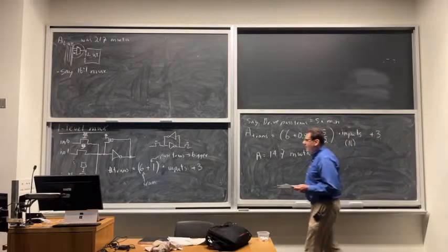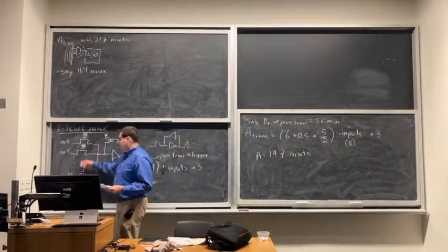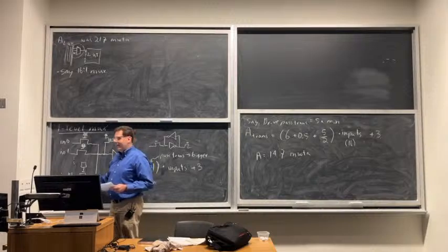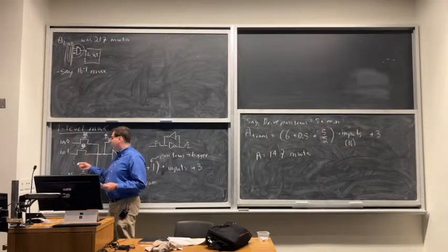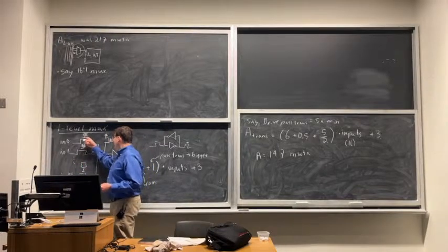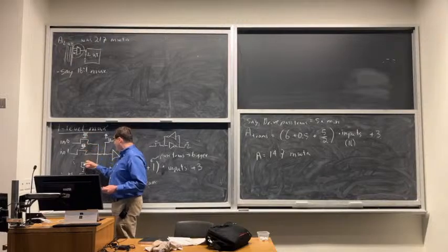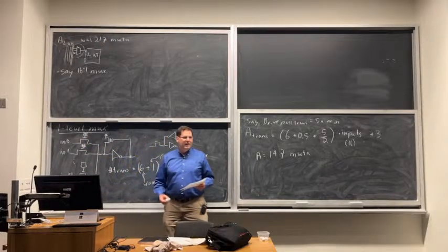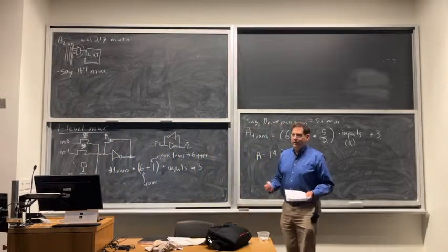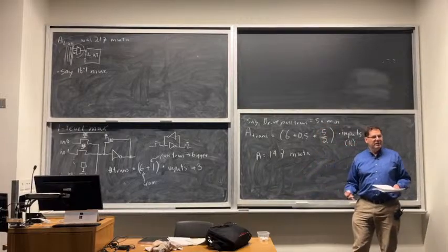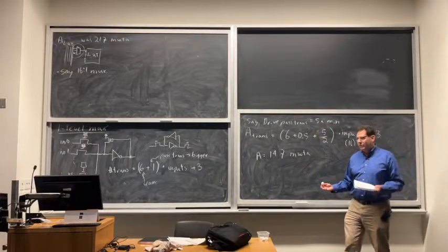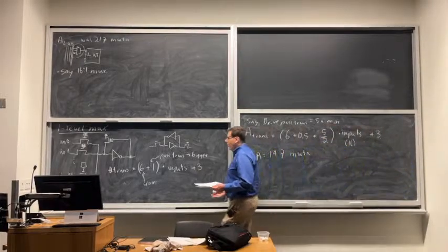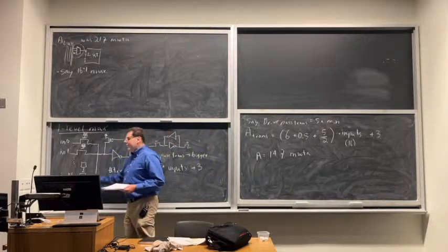So I guess think about these SRAM cells. You can't really do it in fewer pass transistors. In fact, the alternative topology is going to increase the number of pass transistors. Something that's a bit painful about this is that every single pass gate has got its own SRAM cell. And that's actually more area than the pass transistor itself. The pass transistor is doing the work. The SRAM cell is just storing state. So, can we do this with fewer SRAM cells?